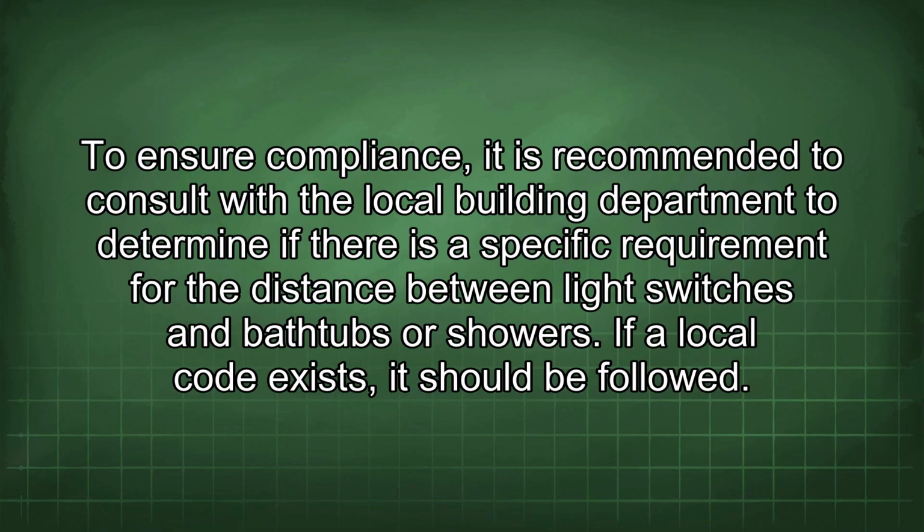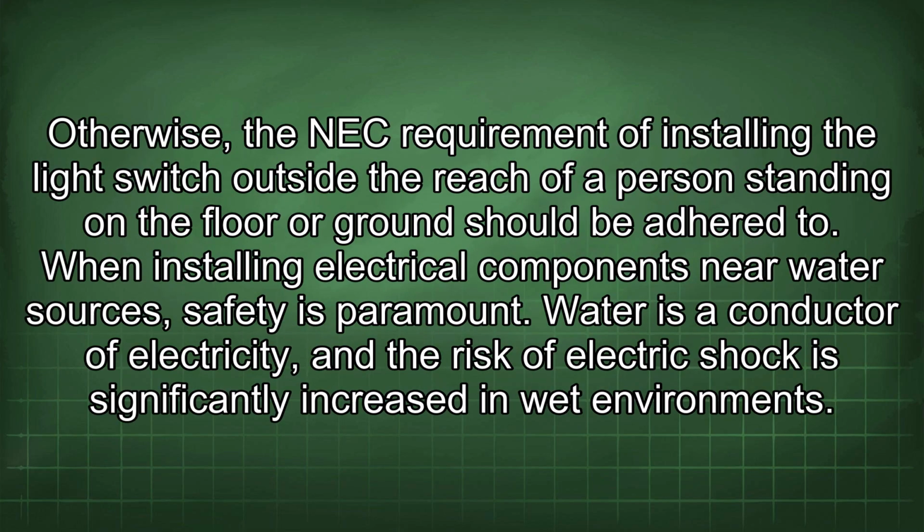To ensure compliance, it is recommended to consult with the local building department to determine if there is a specific requirement for the distance between light switches and bathtubs or showers. If a local code exists, it should be followed. Otherwise, the NEC requirement of installing the light switch outside the reach of a person standing on the floor or ground should be adhered to.